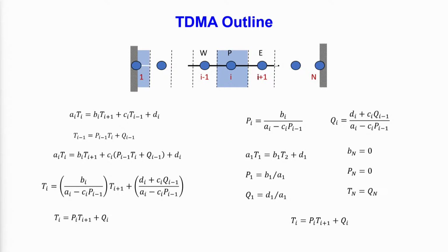So that means you now already have a formula where if you have Ai, Bi, Ci, Di, you can calculate Pi and Qi. For i equal to 1 you already know from the boundary condition. So for i equal to 1 you have A1 T1 is equal to B1 T2, so C1 equal to 0, right, and for i equal to n you have Bn equal to 0 because there is nothing called Tn plus 1, okay, and then you have P1.